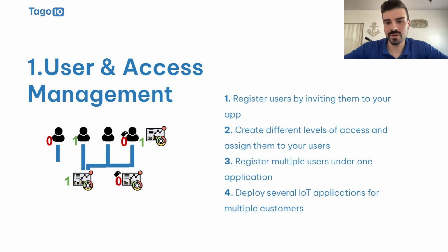The idea is that you can invite users to your application. So you have your admin on TagoIO, your developer page, in which you create your dashboards, you add your sensors, you create your access rules, you set visibility conditions on your Run sidebar. And then you can choose to invite users to access that particular application of yours inside your portal, right? And deploy several applications. So inside your TagoIO account, you have many different profiles. You could have a profile for one application, you can have a profile for another one, you can have a profile for a sandbox, and you can control these profiles, edit resources, distribute them properly.